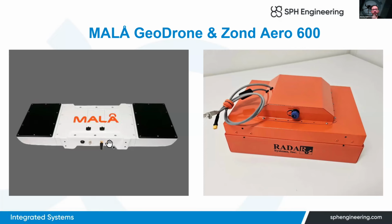It is very important. The GNSS receiver is inside the casing, and that receiver is not RTK capable. So if you need precise coordinates in your data, you need to have a precise flight track or survey track and geotag the data after the flight using only timestamps in the data.